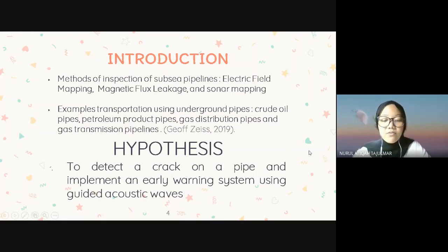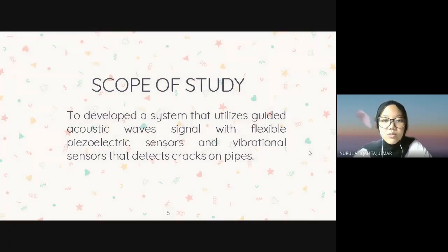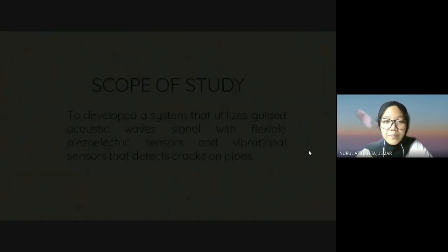So the hypothesis of our project is to detect a crack on a pipe and implement an early warning system using guided acoustic waves. The scope of our study is to develop a system that utilizes guided acoustic wave signals with flexible piezoelectric sensors and a vibrational sensor that detects cracks on pipes. And the coding of the system that we will make will use Arduino software.